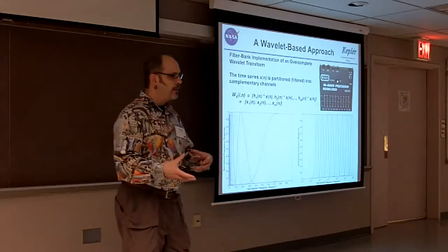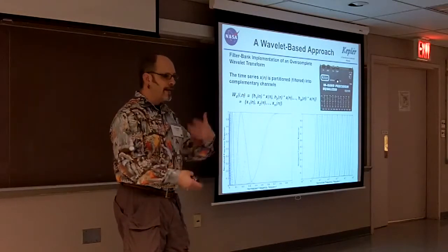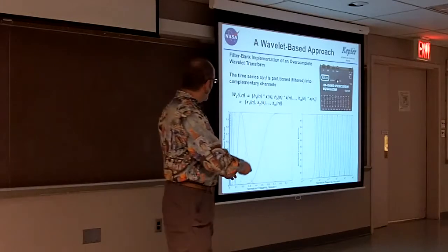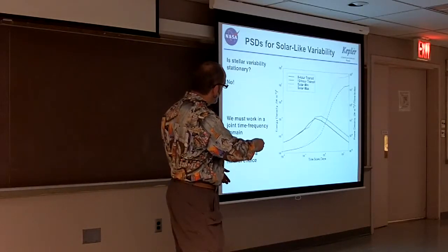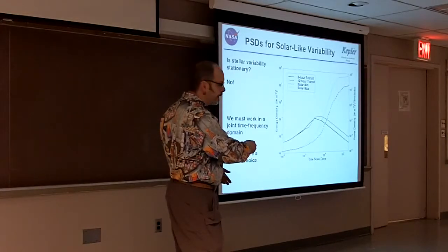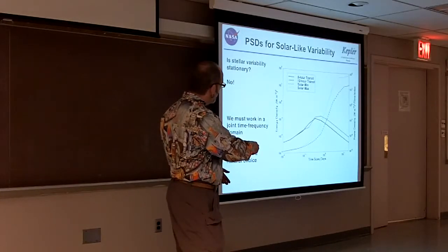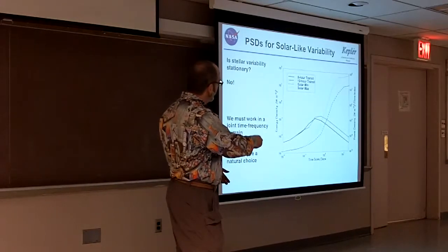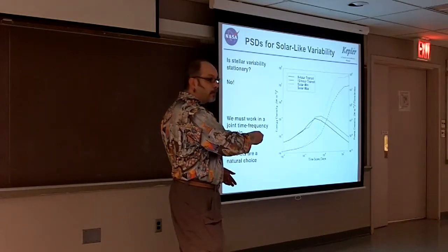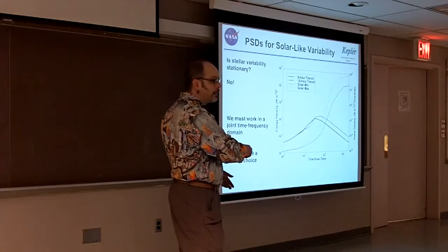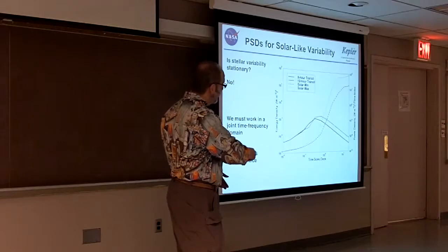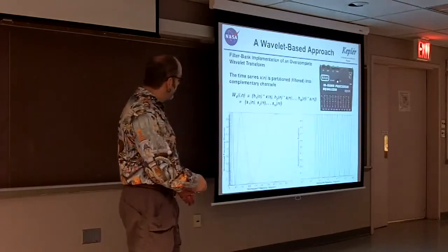Okay, so what that allows you to do then is to look in each of these channels to estimate the noise power in that channel, and then you can whiten the data, which is essentially what you want to do. If we go back here, to do your detection with that whitener, or the power spectral density, you divide the transform of your data multiplied by the transform of your signal by the inverse power spectral density of the noise process. So it means stuff out here isn't going to get much weight. Stuff down here gets a lot of weight. So this is where we're able to detect stuff, in this region. So that's really what it says.